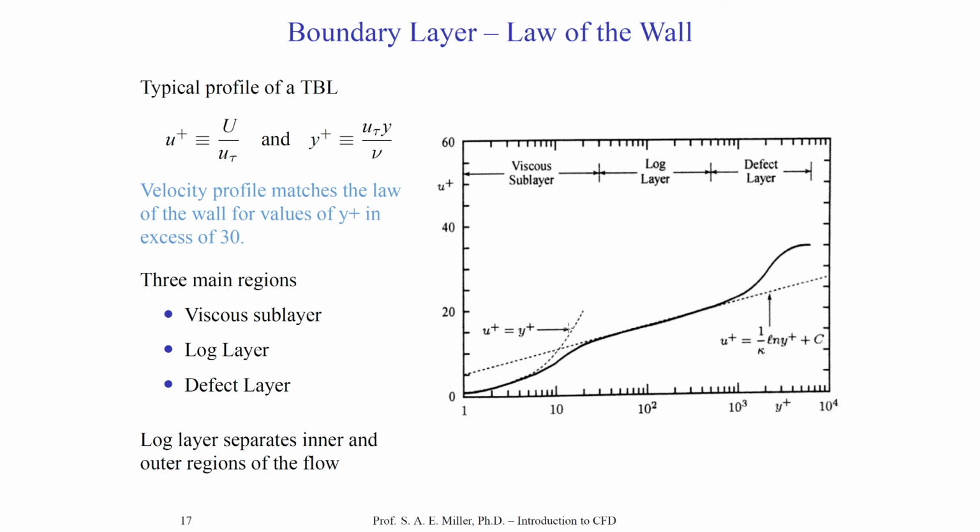Now, very close to the wall, between the wall itself at y plus 1 and roughly 10 to 12, u plus is exactly equal to y plus. Why is that? Because, of course, it is really truly a laminar type flow in this region. That is, the viscous effects in the viscous sublayer are dominating the flow, and we'll find this universal nature of the flow that u plus equals y plus. It's a wonderful collapse of the data.